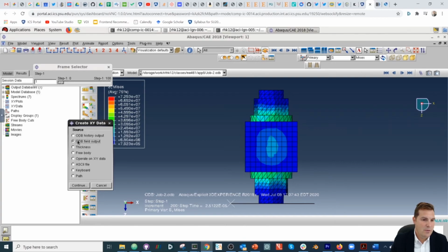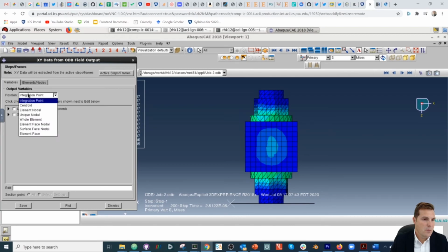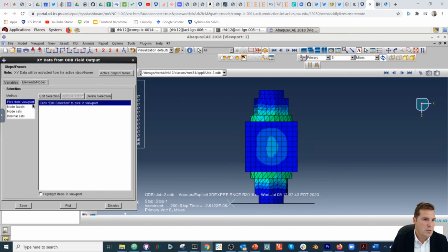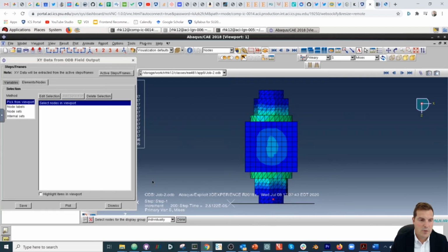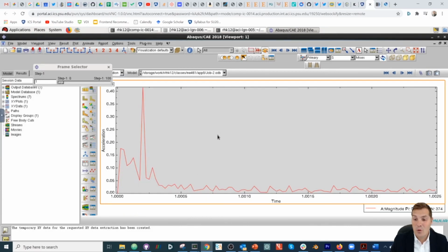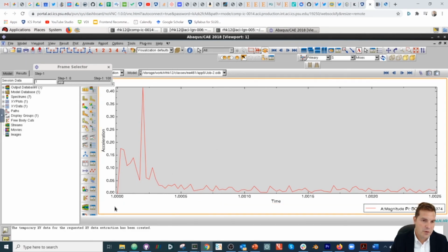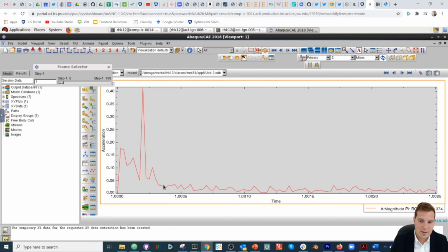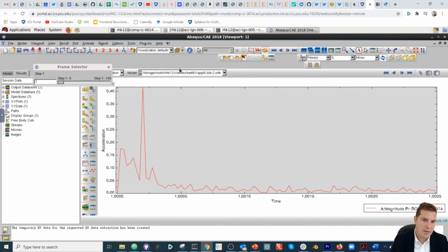If we plot this now the same way we did before with the unique nodal accelerations, and then select a node somewhere down there, plot. And there we see more of what we expect. So at the initial time, we have a really quick, high jump, and it would be pretty interesting to even have more plot steps. So we can see that we separate down here at really 0.0005. So we can probably cut the simulation off here, keep the 100 steps, and we'd have a nice, really smooth curve on the acceleration.